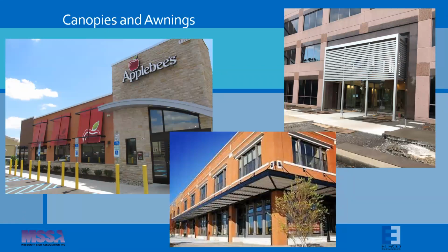This is an example of some different types of canopies. As you can see, there's a wide range of canopies and awnings, most of which are straightforward. Notice the middle picture though. When you have a deep roof hung or even cantilevered awning like this, snow loading and drifting can become the controlling issue.